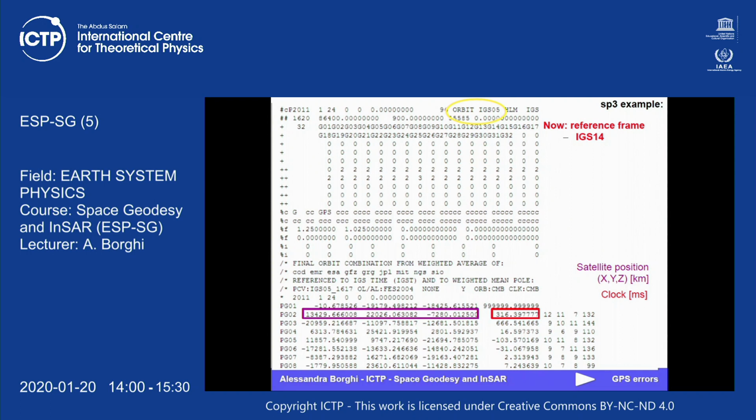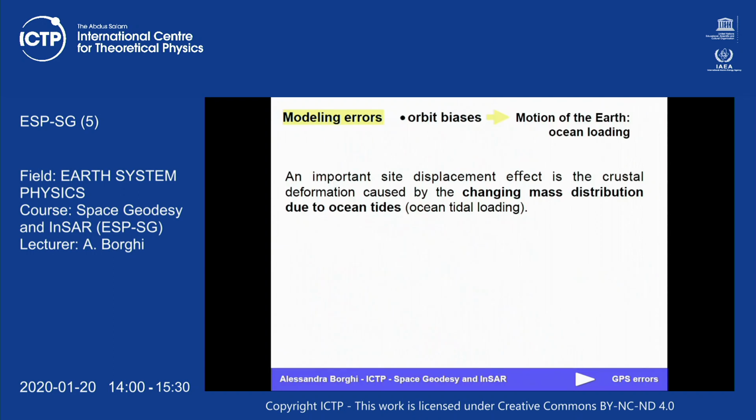We have also information about the clock to correct the satellite clock for each satellite, you see. So in the final orbit, we also take into account the clock correction of each satellite. Just for real-time applications, we don't take into account this difference, and we say, okay, all the satellites are synchronized. Okay, but this file is read by the computational software.